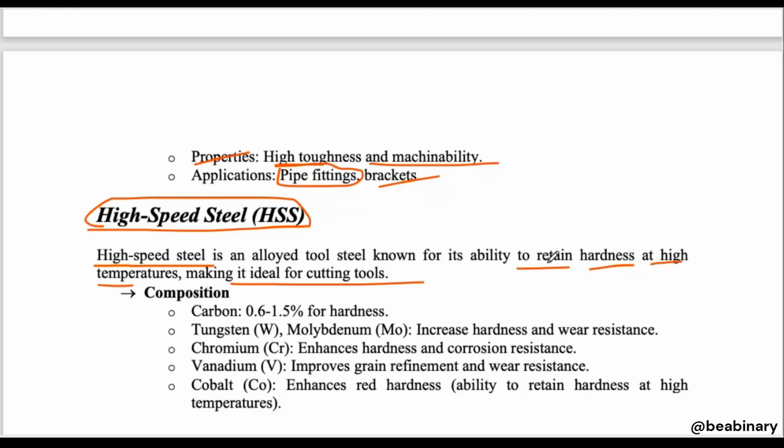Sometimes you have also seen a built-up edge. The built-up edge happens on the face of the tool due to the high temperatures. Due to the heating, the material gets a little soft, and the material being machined gets stuck on the tool.